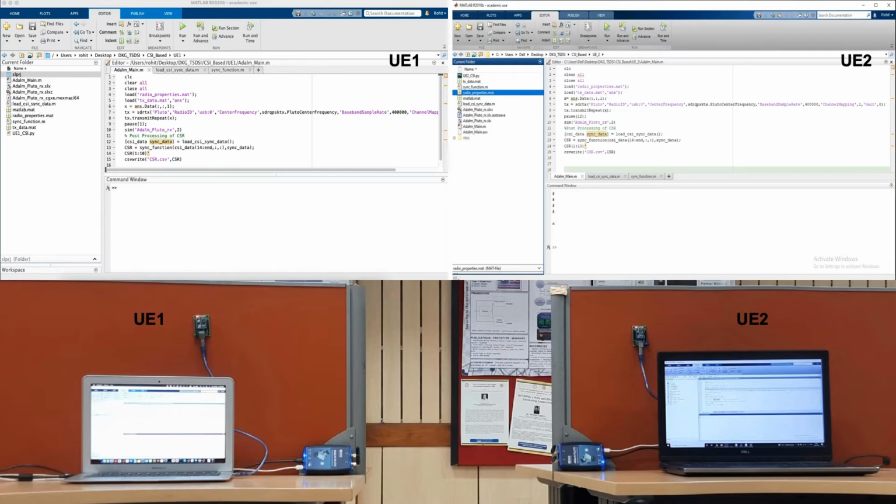The idea of software-defined radio is that the passband signals are directly translated to baseband signals, that is, centered around 0 Hz using a homodyne receiver. So SDR acts as a front end while all the processing on the signal is done on the host system. Likewise, in case of a transmission, IQ samples or the baseband signals are synthesized by the host system and SDR up converts it to the passband.